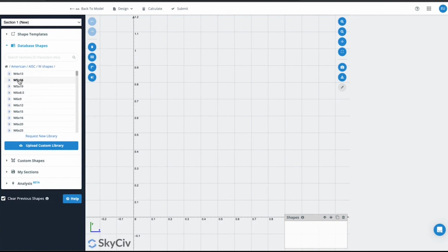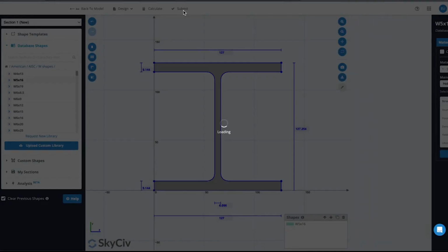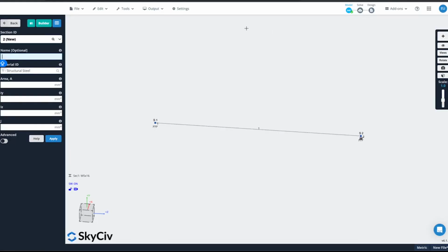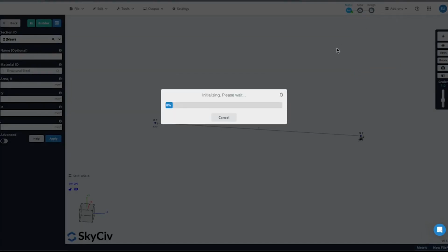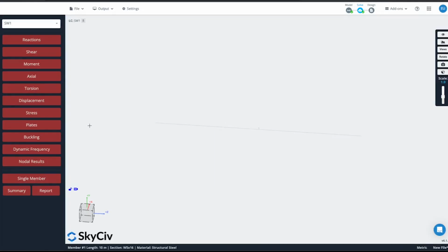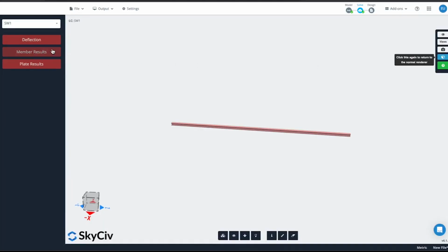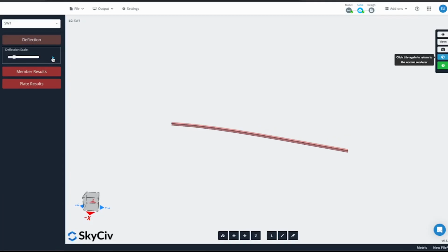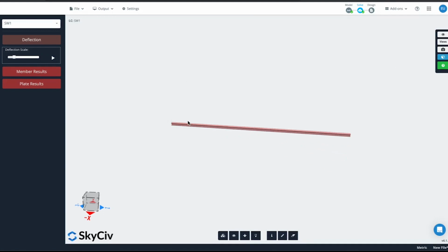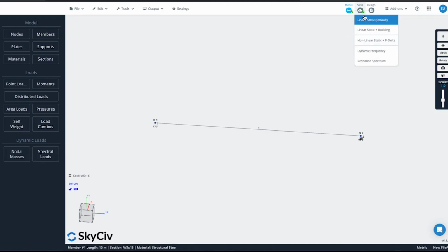And we'll just use some basic I-beam and submit. So now when I go to solve it, if we look at this placement, you can see here it's being depressed, and because of the weight, when it comes to this point right here, it's still fixed, so it can't actually translate. But if I go to the 3D, you see it's being pushed down here, and we can actually see the resultant load based off of this spring member. So let's go to solve,